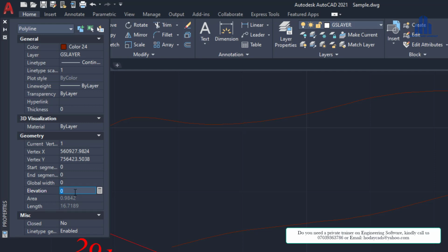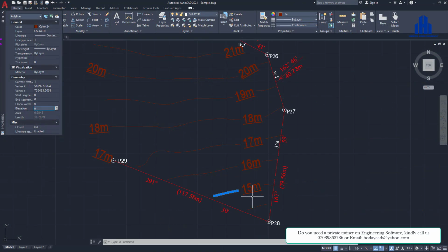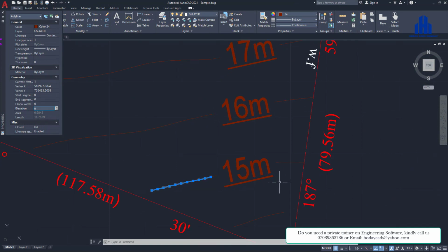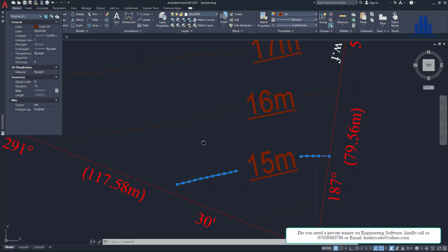So what do I do in those kinds of cases? It might look like a long route, but it is the only thing you can actually do: you have to give those contour lines, as per the inscription there, their specific elevations. Say for instance the elevation for this is supposed to be 15. Remember, I'm still in meters, I haven't converted, so I enter 15. So I've been able to give this 15.